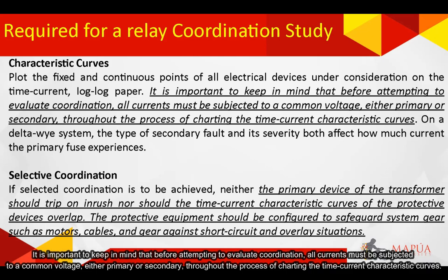It is important to keep in mind that before attempting to evaluate coordination, all currents must be referred to a common voltage, either primary or secondary, throughout the process of charting the time current characteristic curves.